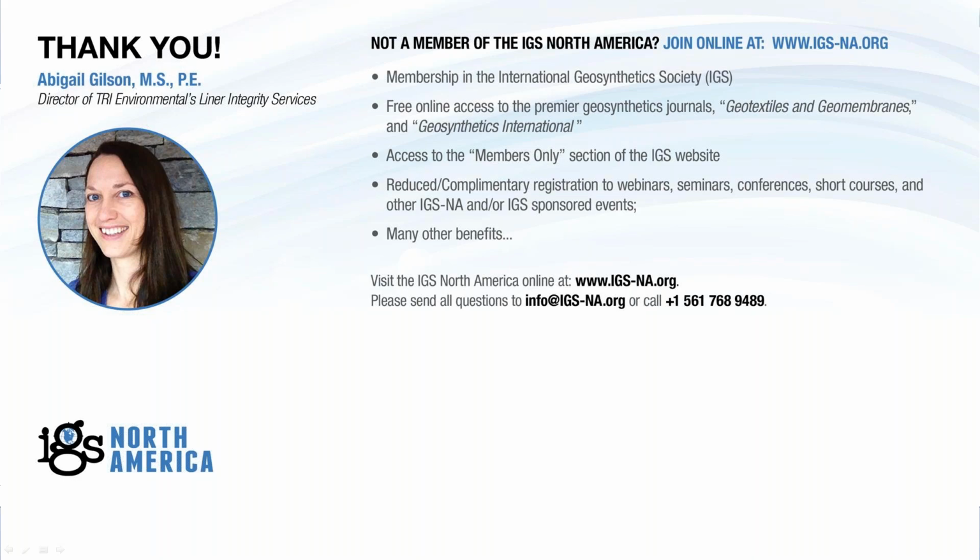People say, oh, well, if leak location was done in the baseliner, that's fine. Well, I don't know what was done in the baseliner. I've been around for enough years to see surveys done horribly wrong, even when they're trying to be in conformance with the ASTM, because the ASTM D7007 is so poorly written. So if a good survey were done on the baseliner with confidence, like using the methods that we talked about today, I would feel more comfortable with not surveying the cap, because you know the baseliner's intact.